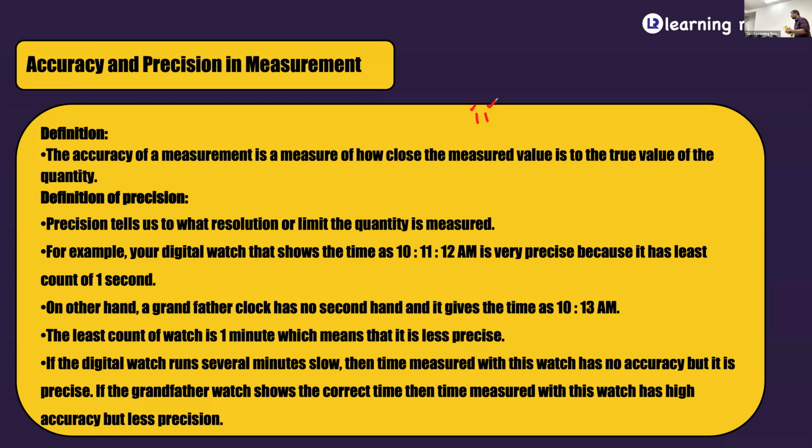See, let's forget about inch as of now. Let's say I'm taking it in terms of centimeter. I keep my 0 here. I'm trying to measure it here. So what is the number you are able to see? 21, is it exactly falling on 21? Can you tell me with the decimal value, 21 point what? Is it exactly falling on 2 millimeter? No, right? It is between 1 and 2, right? So you're able to understand.